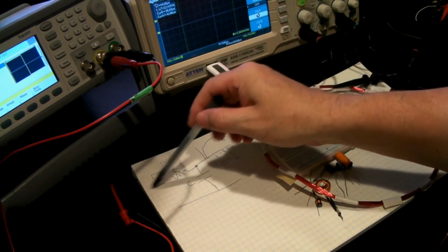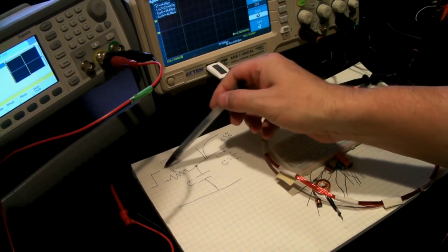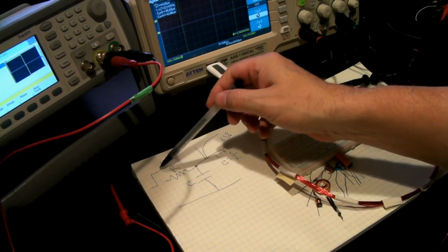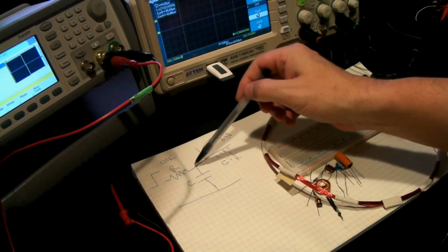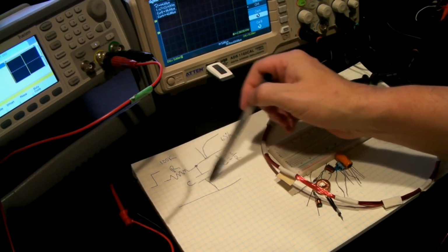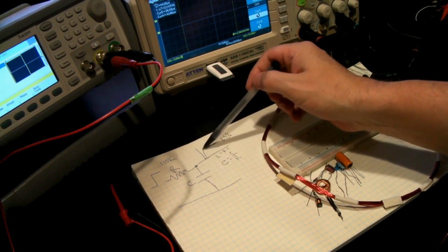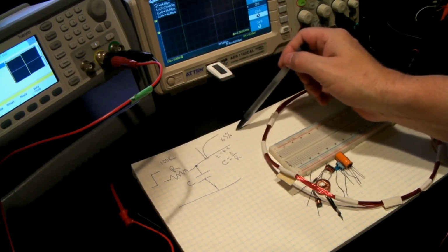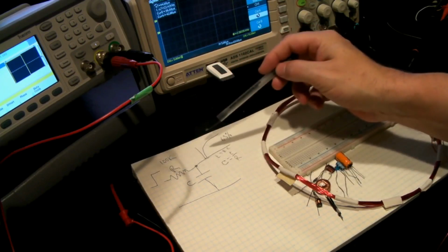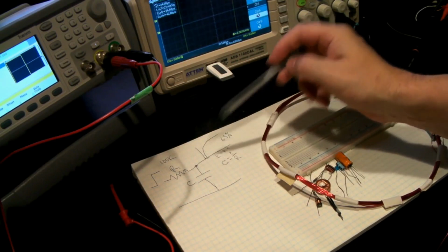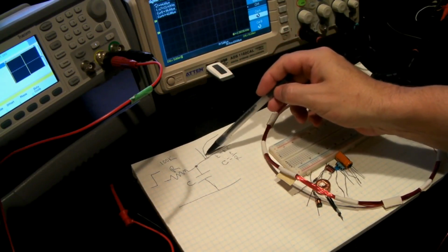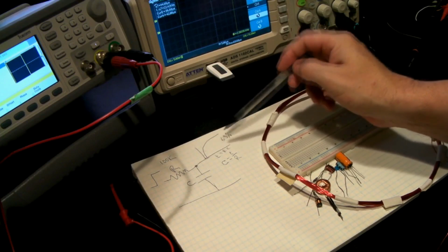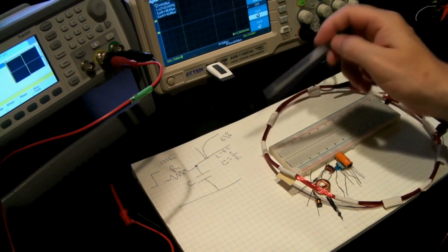So the minute I put this pulse up to, say, a 1-volt pulse or something like that, the capacitor will immediately start charging with the RC constant. When it reaches 63% of the full voltage, or in this case 630 millivolts, because I'm going to give it a 1-volt input, then that time from when we applied the edge to when we reach there, put into this formula, will give us a time constant so we can figure out the capacitance.